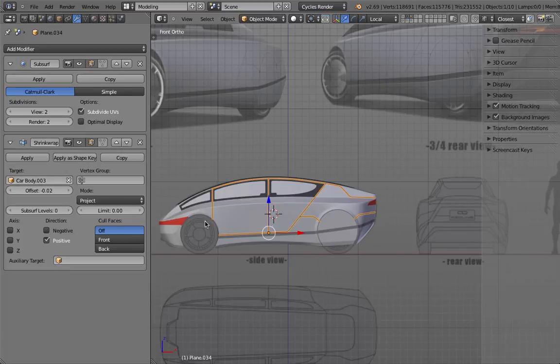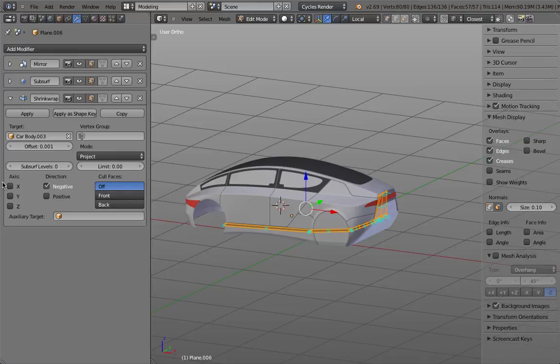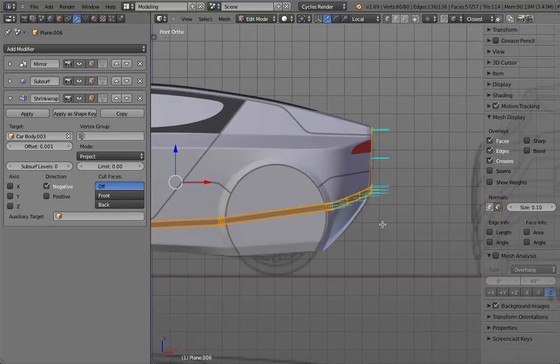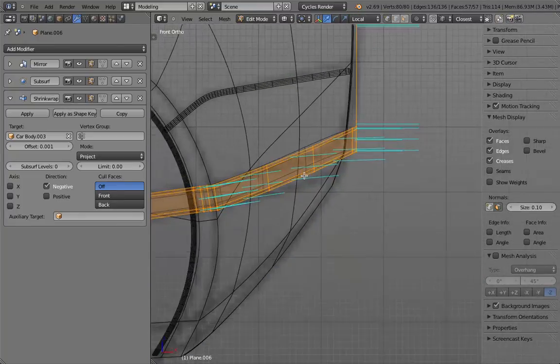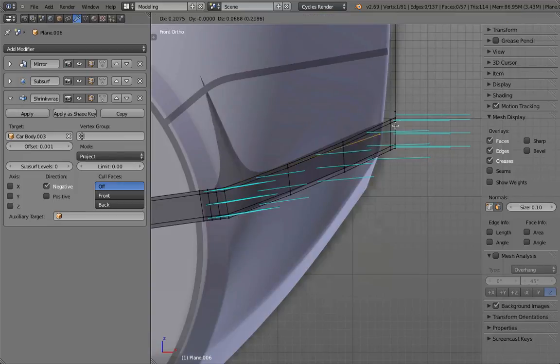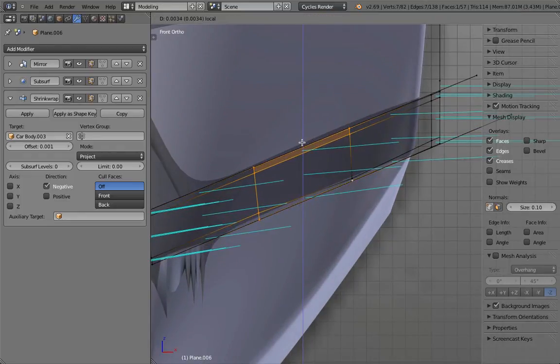And if, for example, you would like something to flow around your object, like this part, then you should best not use the axis constraint because it will not allow you to model the surface around your object. And then you can basically build a piece of clothing you put around your car and then snap onto the object. The only thing that's very tricky sometimes is, for example, you see here in my case, if I draw some lines, those are helpers, I can see that actually those parts here I have to move up a little bit.